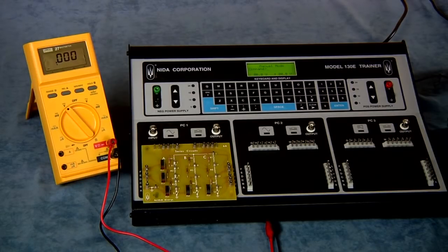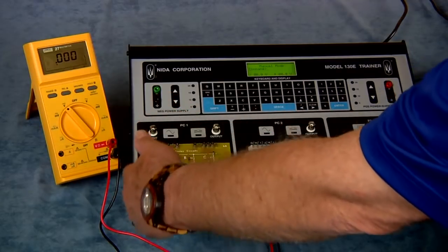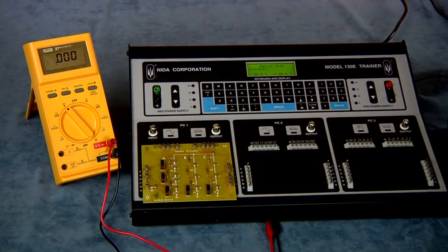We've got basically, I'll be working with the A series sequence. That's the series circuit that's on the left side of the board. It's comprised of a 2K, a 1K, and a 1K for the 3 resistors, for a total of 4K ohms, which gives us about 3 milliamps with 12 volts being supplied. So we should have the 6 volts across the 2K, as we calculated from the PDF, and across the 2 1K resistors we should have 3 volts apiece.